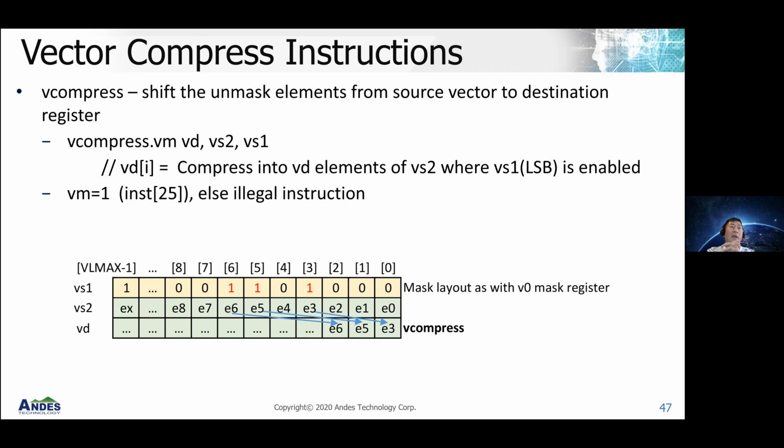But anyway, we managed to implement the vcompress instruction. Even for 512 elements, so if you have LMUL equal 8 and the element width is 8-bit, then you have 512 elements. And now you try to compress 512 elements into the destination vector register. And so for Andes, we managed to implement that in 13 clock cycles.